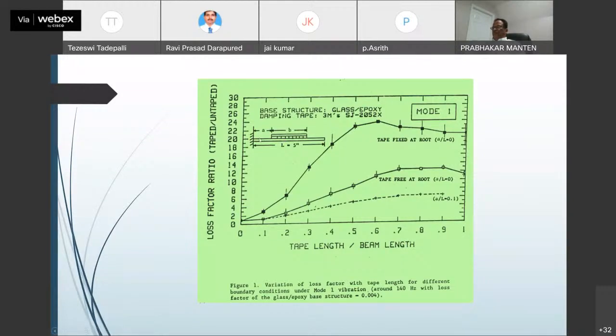Again, in this mode, the best region would be at the base region, effectively the first mode. For the second mode, you have to be away, somewhere here. The application would kill the second mode of the rotor blade. And for the third mode, at this point and this point of the cantilever, not near the node point or the free end. Just putting something at the free end would not help. It will not stress the element in the center with strain energy created. Strain energy has to be created for those molecules and the entanglements to move back and forth for effectiveness.